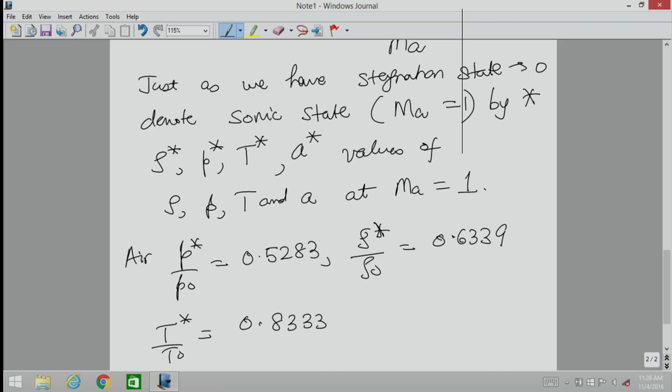So therefore these pressure changes in liquids, of course, will be very drastic. You don't need half the pressure drop; it will probably be a fraction of the Mach number. But for gases, even a reasonable drop of pressure can lead to flows which are compressible. Okay, so that's why one tends to use these things.